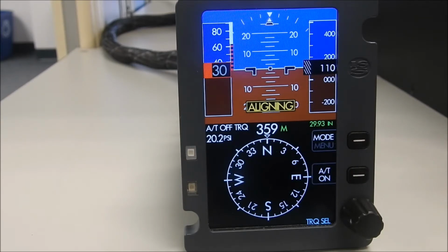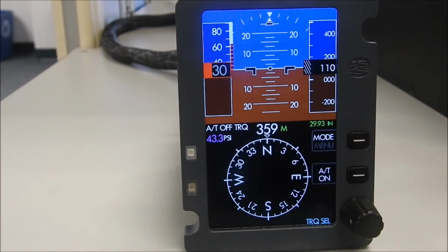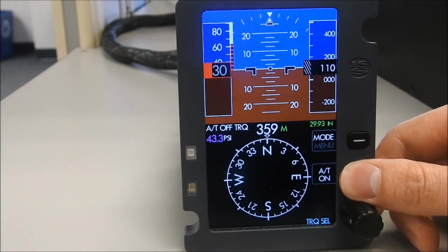Autothrottle is only available on ground in takeoff mode. Takeoff mode is activated by pressing the go-around switch on the power control lever of the PC-12. When that button is pressed, an automatic torque value calculation will occur based on the Pilatus AMM. The torque will turn magenta to indicate the calculation has occurred. Once performed, Autothrottle can be turned on using the AT on switch.